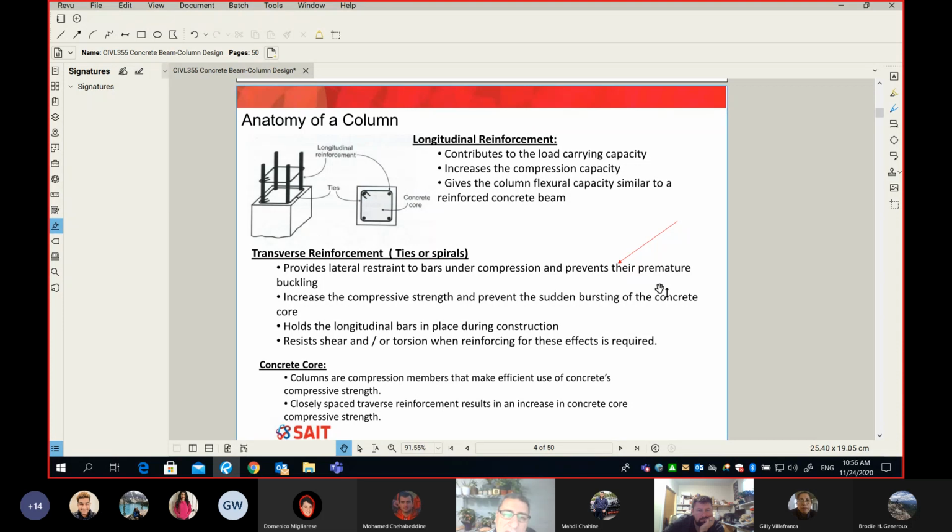To the outside, there is air, and there is very little cover, like 3 or 4 centimeters of concrete, and simply the bar will buckle to the outside, if you agree. Yeah, I never thought about the concrete on the inside. That makes sense.